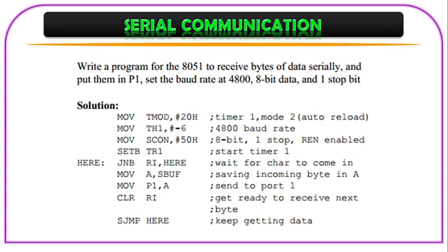Receive data serially and put it in port 1. So the initializations are the same: the timer control register, and then the timer count, and then SCON, and then set the timer, start the timer.